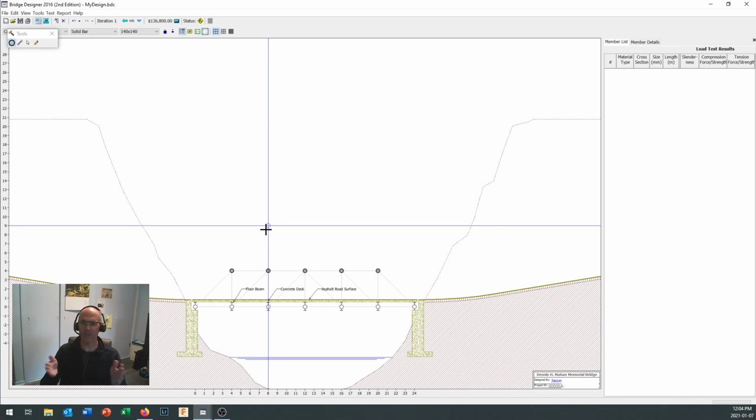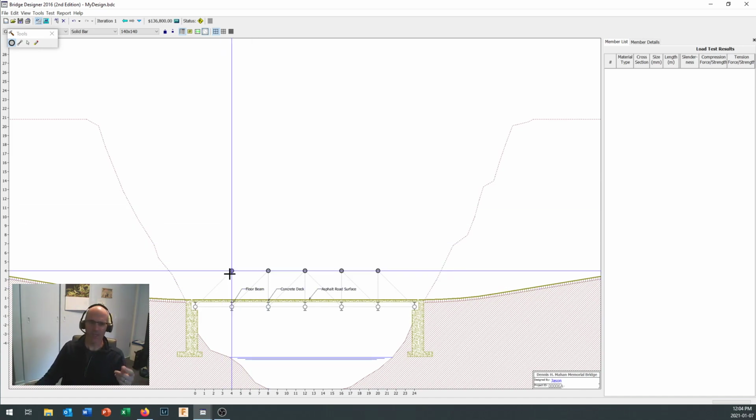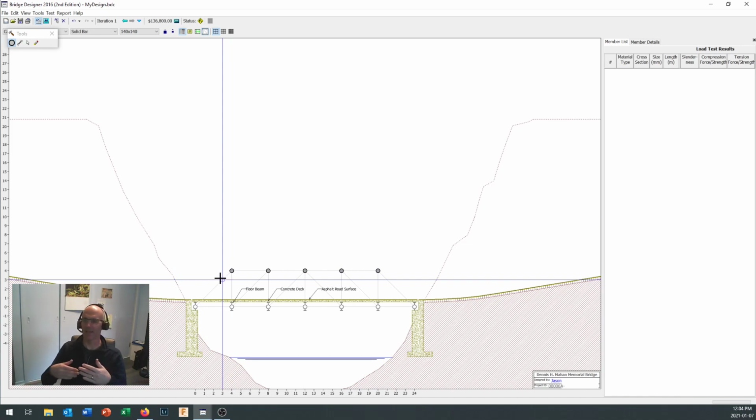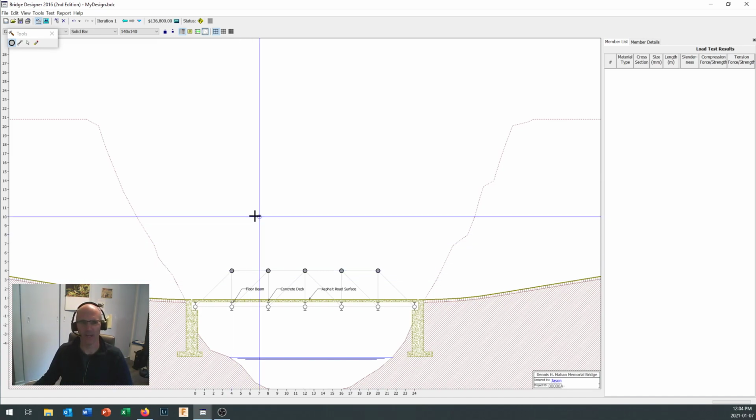So when we're doing our truss analysis in class, we're going to use these nodes to connect members. It's important to think about the fact that those nodes are free to rotate about each other when we do our analysis. That also explains why you see so many triangles when you put your bridge together.